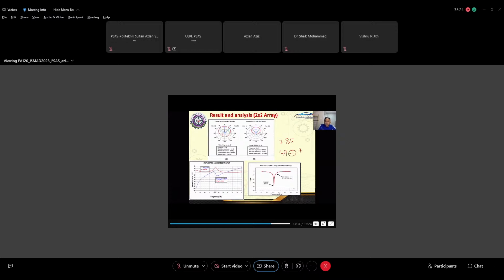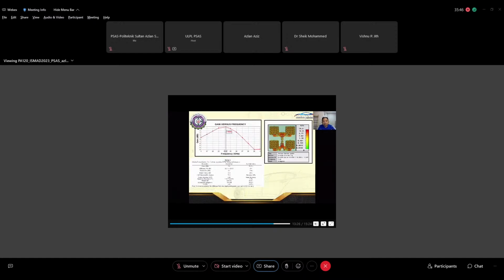Minus in this condition indicates that our antenna is influenced by the capacitive output. So for the S11, it is still manageable, still in good condition, with 2.42 as the center frequency and 2.5 in the range of expected operating frequency, by focusing on this simulation S11 return loss graph.